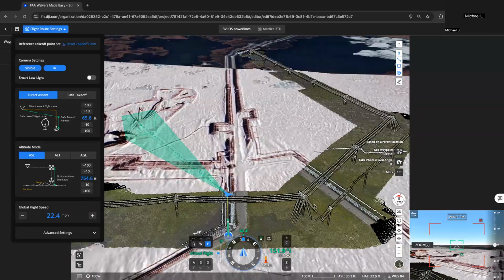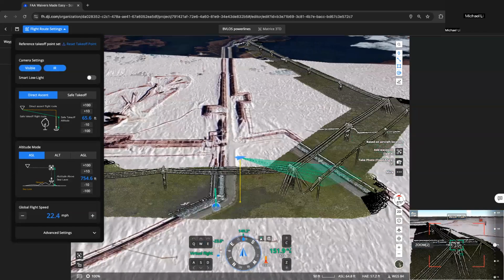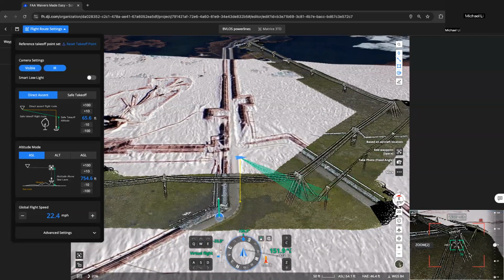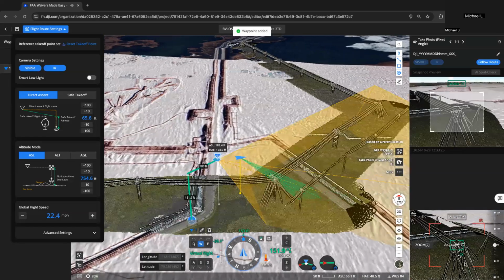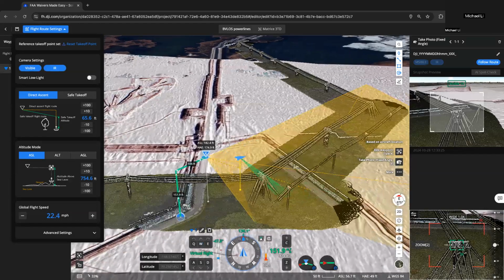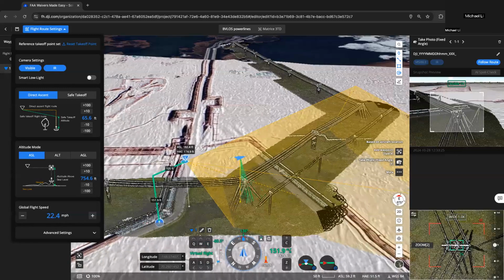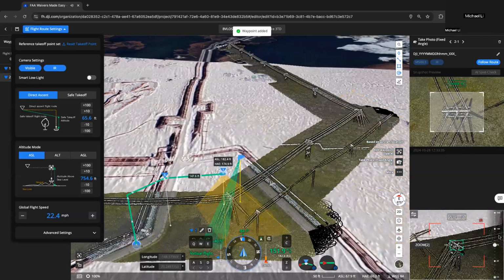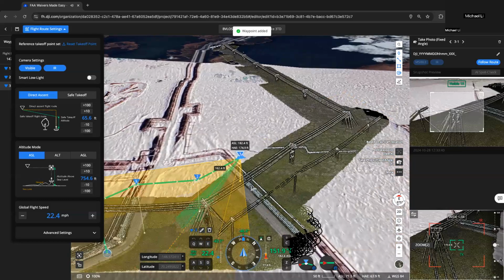So you can see how this can be useful if you have your beyond visual line of sight waiver and you have the task area or the area that you're planning to fly mapped out using our LiDAR camera L2 and uploading that data into Terra, processing it, and then uploading it to Flight Hub 2. So right now I'm planning a mission inspecting some power lines. As you can see, I'm about 150 feet right here, and I'm able to essentially fly to each power line and inspect it, choose my camera angle. Every time I snap a photo, it drops a waypoint.